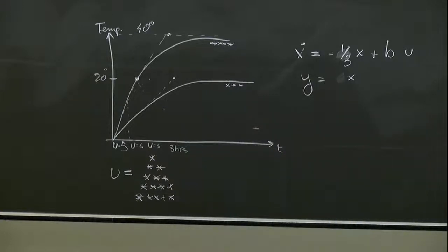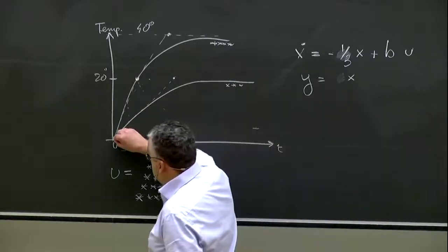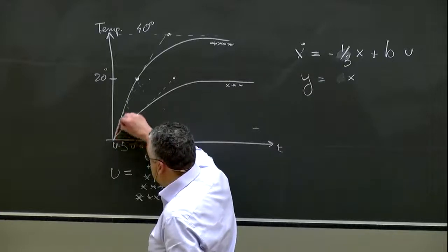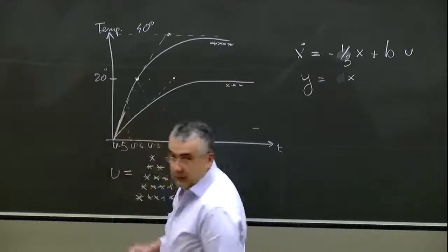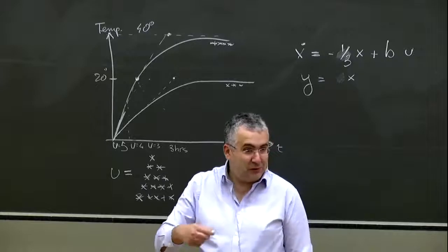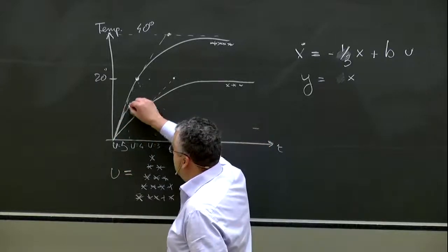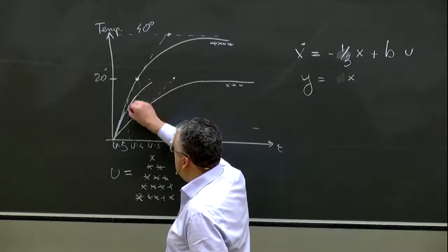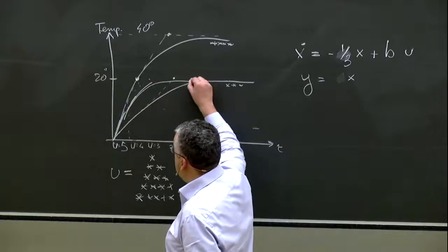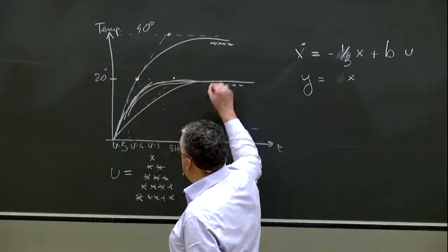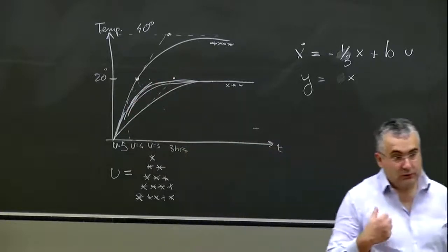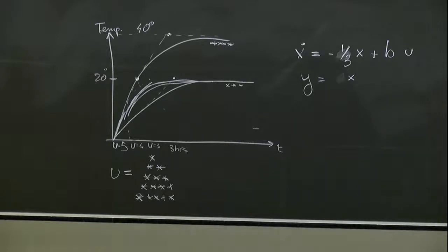But by doing this feedback, what happens actually is that by setting this to 5, you get the temperature to rise quickly, then you set it to 4, right? And then you set it to 3, and essentially what you will get is something like that, okay? So essentially what you see is that the shape of your response is actually changing, okay?